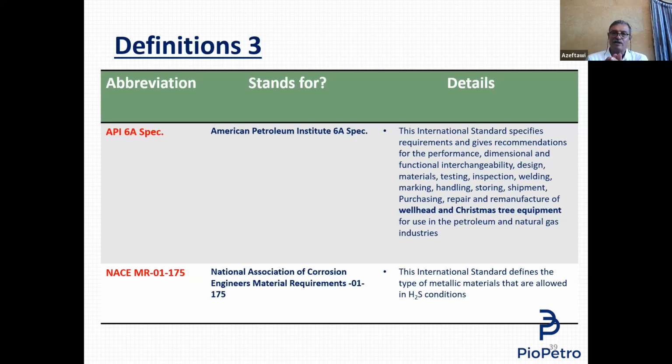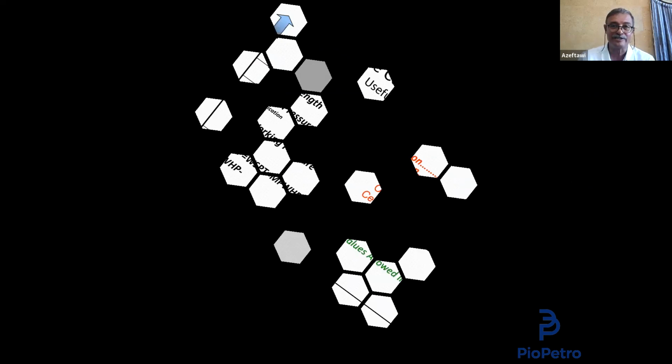The problem we have now is that this BOP has already been exposed to H2S through the material itself. It destroys the material of this BOP. So the best scenario, I believe, to do with this BOP is to bring big plastic bags, put it inside, close it, and put it aside, beside the well. The BOP is not suitable for work now. The H2S has destroyed it. This is very dangerous. Please don't play with it.